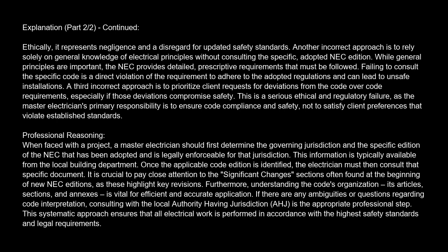Professional reasoning. When faced with a project, a master electrician should first determine the governing jurisdiction and the specific edition of the NEC that has been adopted and is legally enforceable for that jurisdiction.